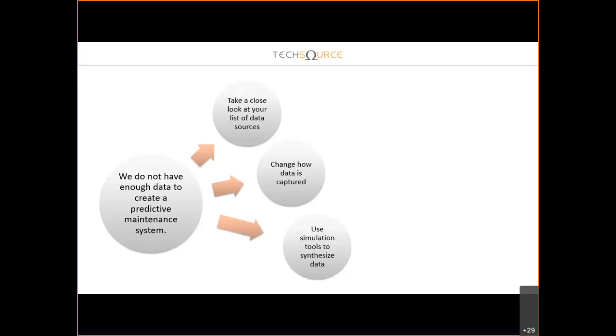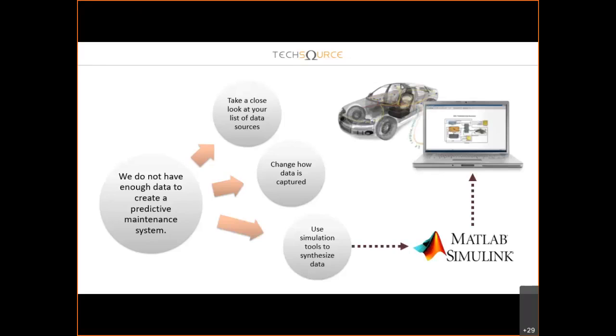Last, you can use simulation tools to synthesize the data. For example, you can generate data using a simulation tool such as our product MATLAB and Simulink, and you can combine that data with the sensor data, if available, to build and validate predictive maintenance algorithms. This is done by creating models in Simulink that cover the mechanical, electrical, or other physical systems to be monitored. You synthesize the data by modeling the output readings and validating against the measurement data to ensure the model is calibrated. This can be done at the component level first, then later at the system level for a complex system.